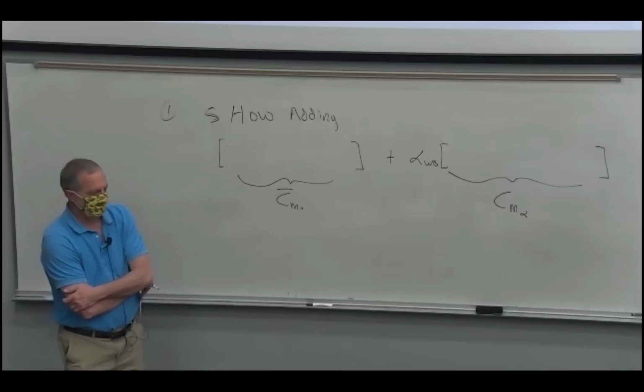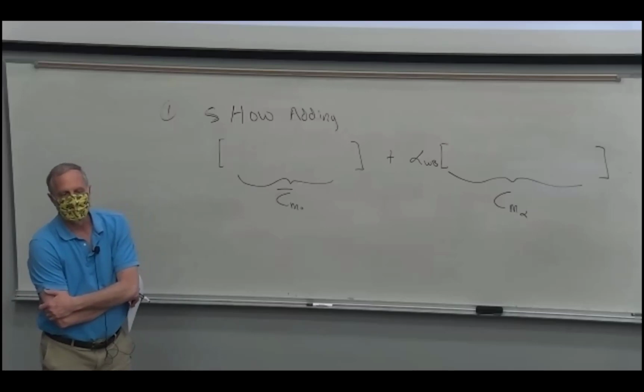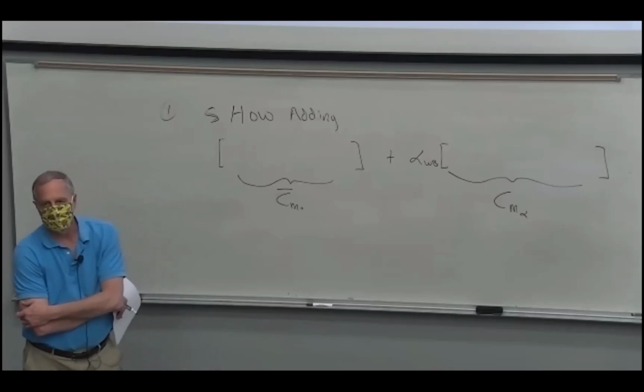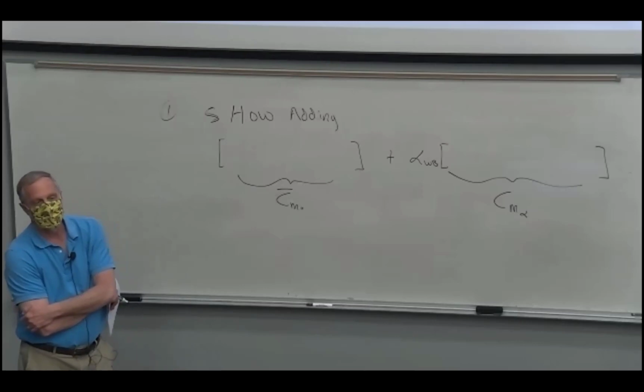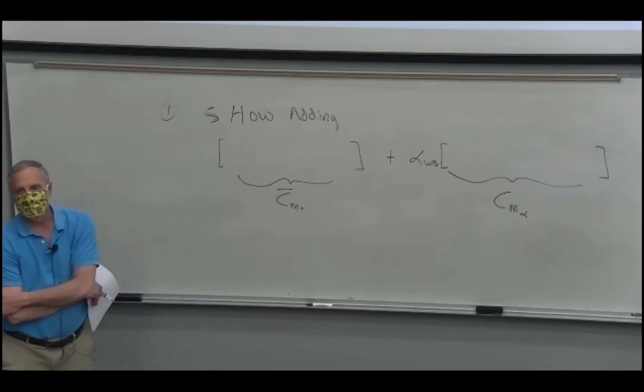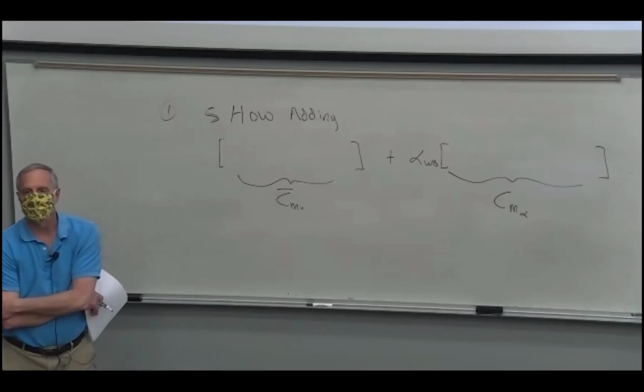But everything should match what we did in the previous homework here. And the difference between in class and the canard is that for the horizontal tail, it's downwash, so we have minus signs for that. And for the canard, we consider it upwash. So there's plus signs for that. So that might be what you're talking about. Yeah, so there's like 1 minus d epsilon d alpha for the horizontal tail, and for this, there's 1 plus d epsilon d alpha.